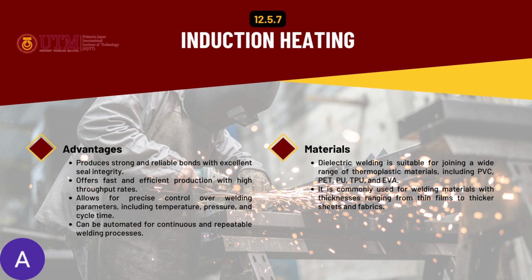Then for the materials used, dielectric welding is suitable for joining a wide range of thermoplastic materials including PVC, PET, PU, TPU, and EVA, and is also commonly used for welding materials with thicknesses ranging from thin films to thicker sheets and fabrics.